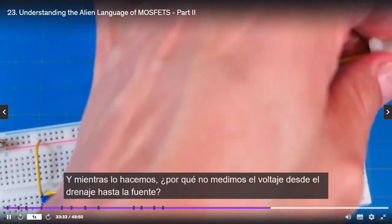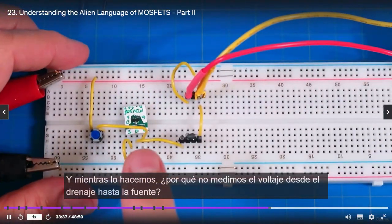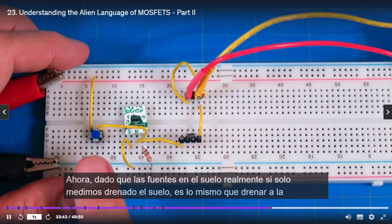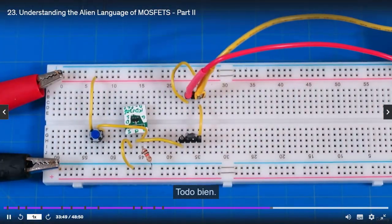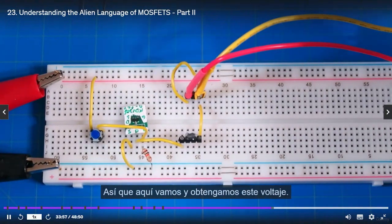And while we're at it, why don't we measure the voltage from the drain to the source? Now, since the source is at ground, really, if we just measure drain to ground, that's the same as drain to source. So let's watch that go to 0. So let's get another meter. All right, got another meter. And let's get another connector. So here we go here. And let's get this voltage.